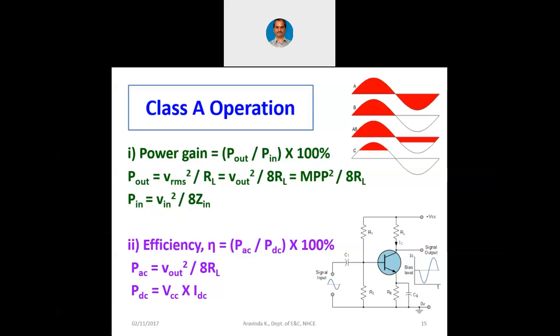For example, let us say as soon as the power amplifier is turned on for a public function or a musical concert, let us say the singer is not yet singing by taking the mic, or the speaker is not yet speaking. Even then, the amplifier is turned on and drawing power continuously, even during the absence of the input signal as well. That's why I have been calling this the static power consumption of the circuit.